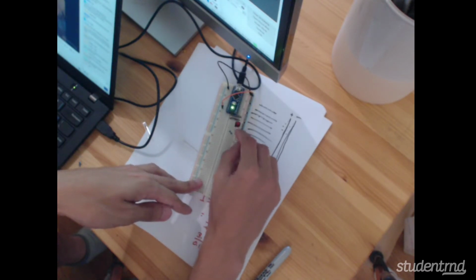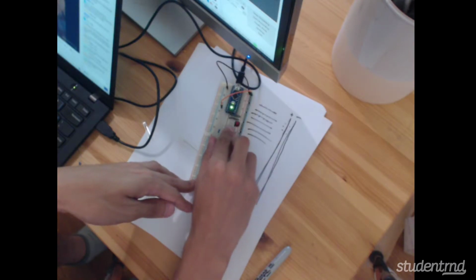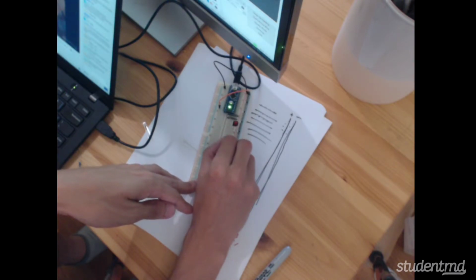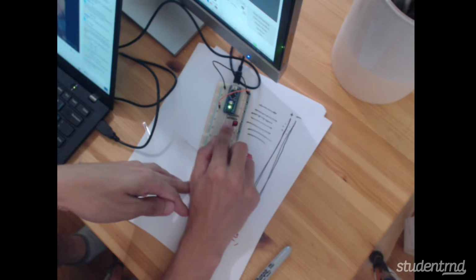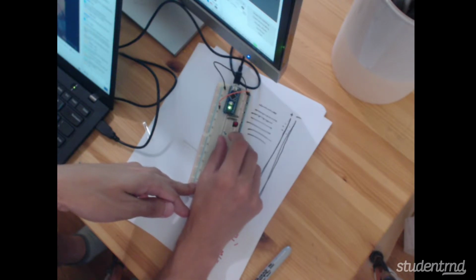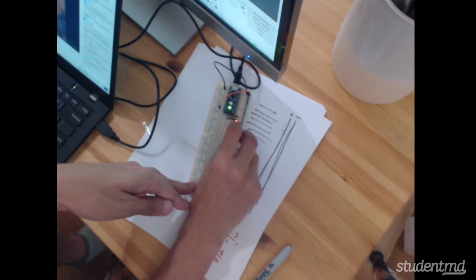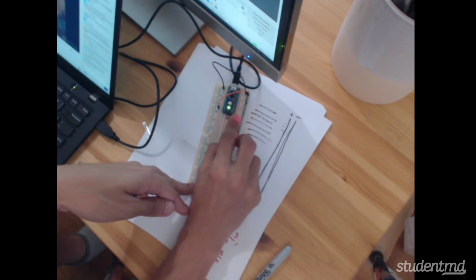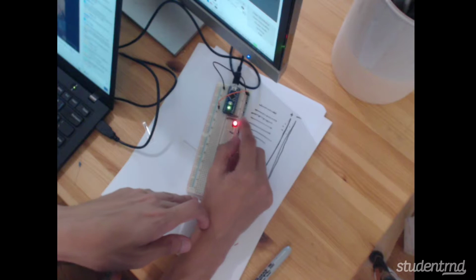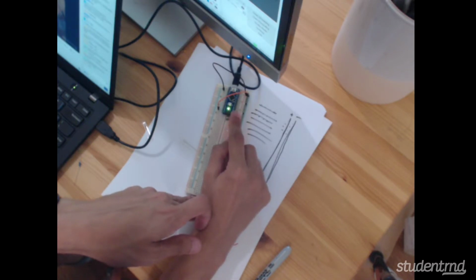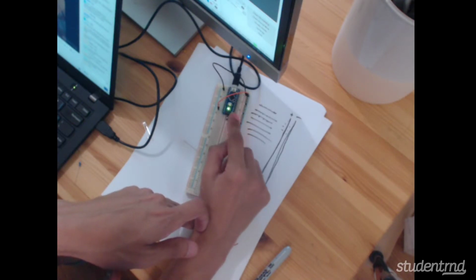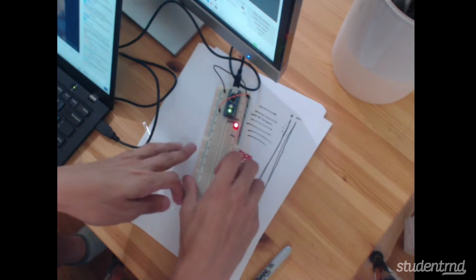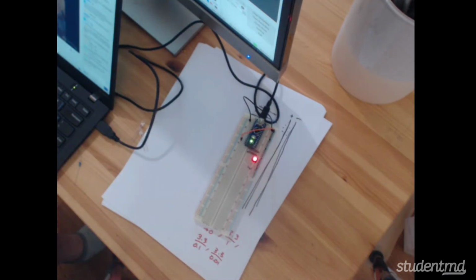The reason for that is because I'm pretty sure that it'll work fine, and we can do the math afterward and confirm. So what I'll do is connect this resistor to one pin of this LED. Now remember, I could just touch it directly to the LED, but instead I'm going to touch it to this side of this leg. So now this is connected to this LED on the positive side. And then I'm going to connect that through to the negative side. You can see the LED lights up. Now the nice thing is this LED is a lot less bright than before, which means it's probably not going to burn out. And it's not cold, it's really warm in here, but it's not burning my finger to have my finger on it, which means it's not really at risk of burning out anytime soon.